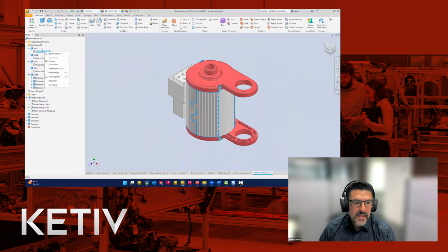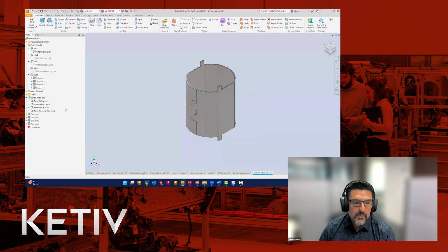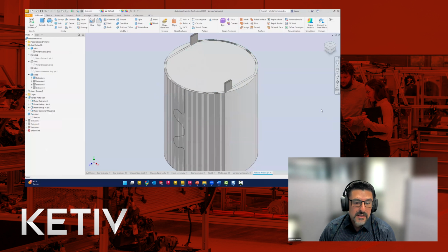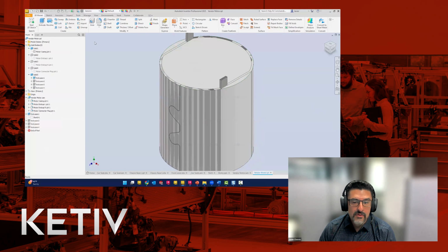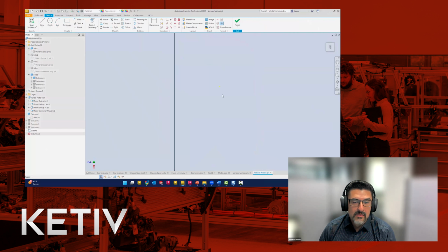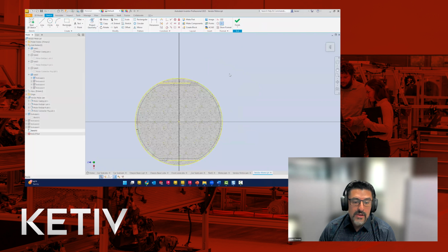And so we're going to isolate the casing now as a body, and we don't want to see the other stuff. And I do want to bring in maybe the box, or the cylinder, that's going to represent the casing. And you can see there's an overlap there. What we're going to do is sketch on top of the solid and use just regular CAD modeling tools to cut away the information. And we can project the geometry from the casing so that we know where that cut is exactly, and continue to use just common sketching tools.